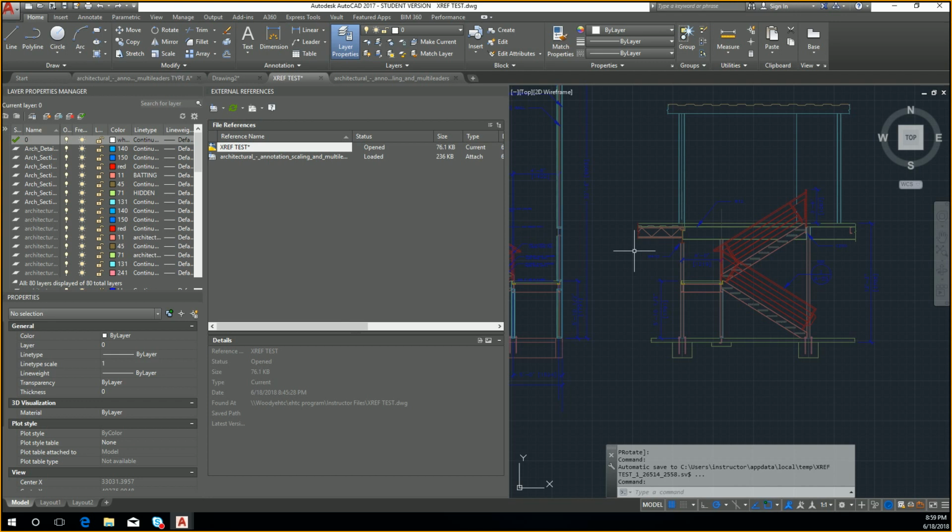See? So the first one's no longer a block. You exploded it. The other ones were still the linked block things, so they will all redefine. So that's working with the block side. Sorry, insert side. External references is something different. If you want to play with that one, you have to explode all these blocks first. So we just pick all of them.